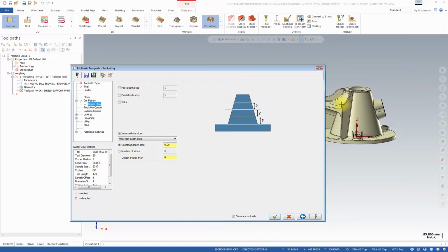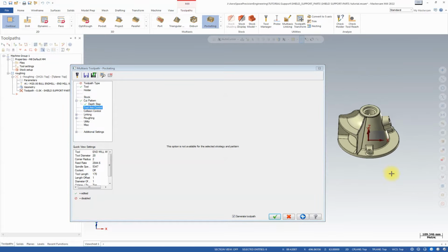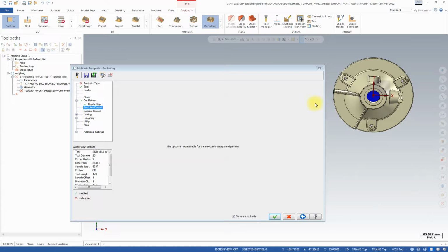As I mentioned, because it's roughing, there is nothing to control your tool axis, and the tool axis is being controlled by the shape of the floor. As you see in this example, my floor is a 2D face, a flat face. So because we have a cut pattern based on the floor, offset from floor, all my cuts will be 2D motion. It's still 5-axis code, but all of them are going to be in 2D.